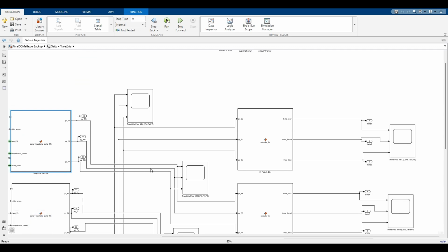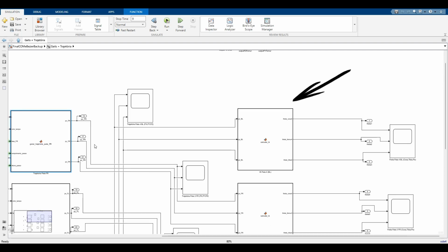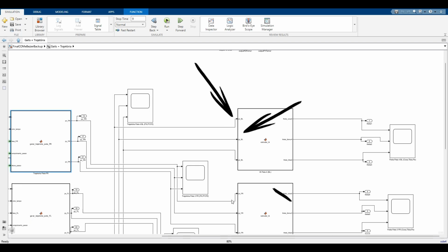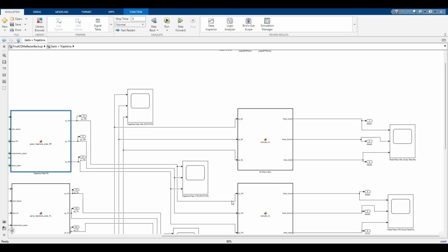These coordinates serve as direct input to the inverse kinematics module, which computes the joint angles required to position the leg accordingly. For each leg, the inverse kinematics algorithm is responsible for solving 3 rotational angles: theta coxa, theta femur, and theta tibia, corresponding to the hip yaw, hip pitch, and knee joints, respectively.